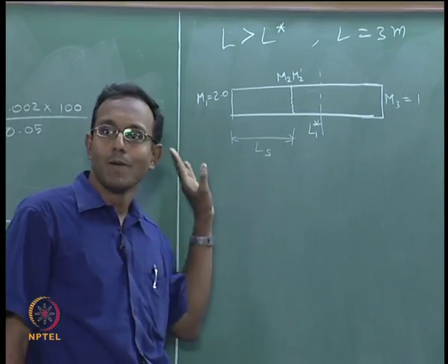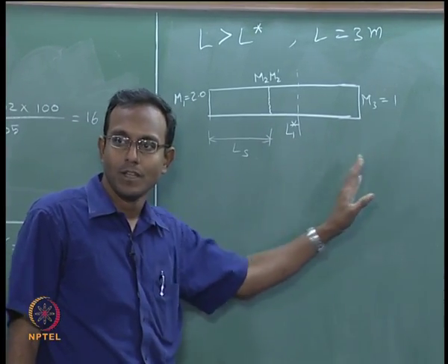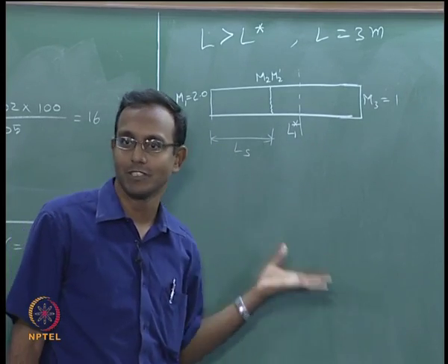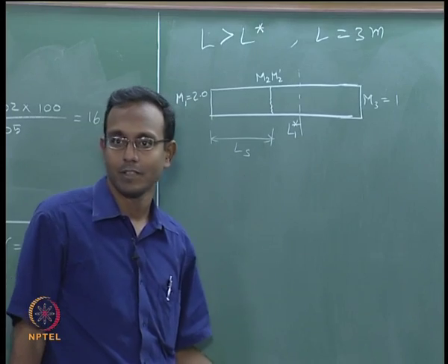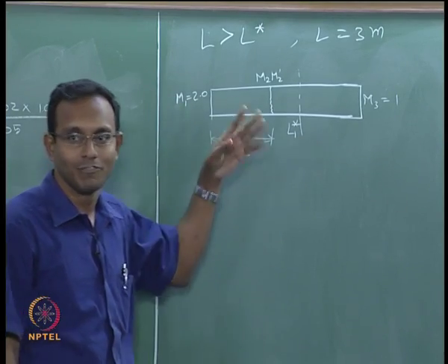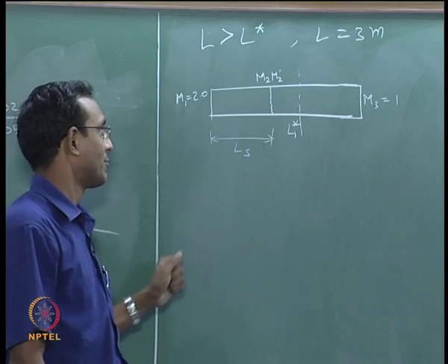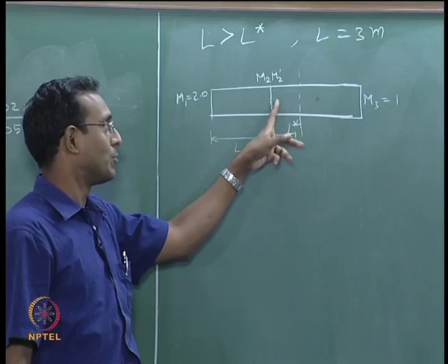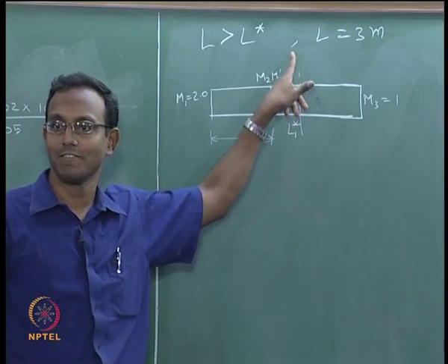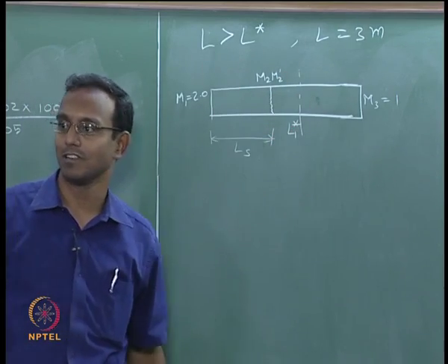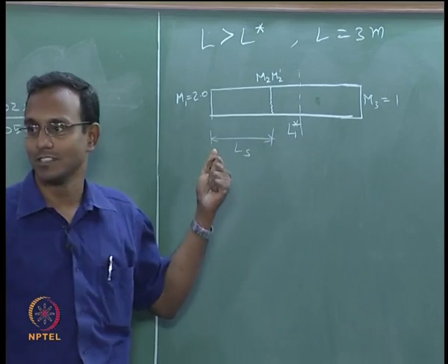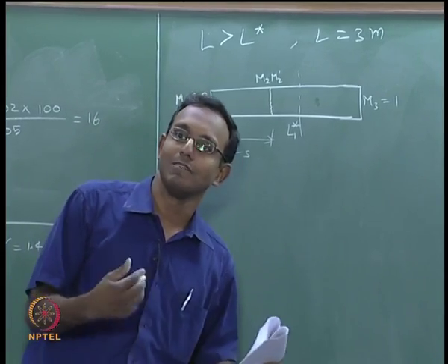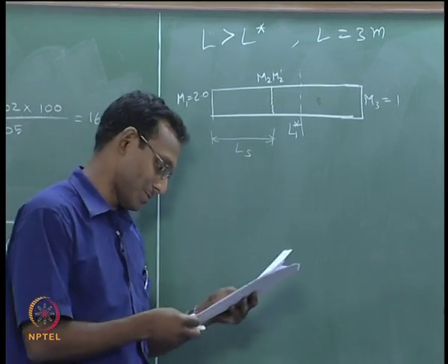That is the overall thing. I am just doing Mach number variation in my tube. Of course, I know that once I know Mach number distribution in my tube, I can find any other property because I have Fanno flow tables with me. For a given Mach number, I can just go and find any other property. If I want to find say somewhere in the middle, I can just go and calculate from m2 prime, I went so much downstream with this f and dh, I can solve that problem, it is not very difficult to solve. And if I want p by p star whatever, I can get every number, so I can change pressures also across. So, I am not solving those, but I will probably give you those as exercise problems.